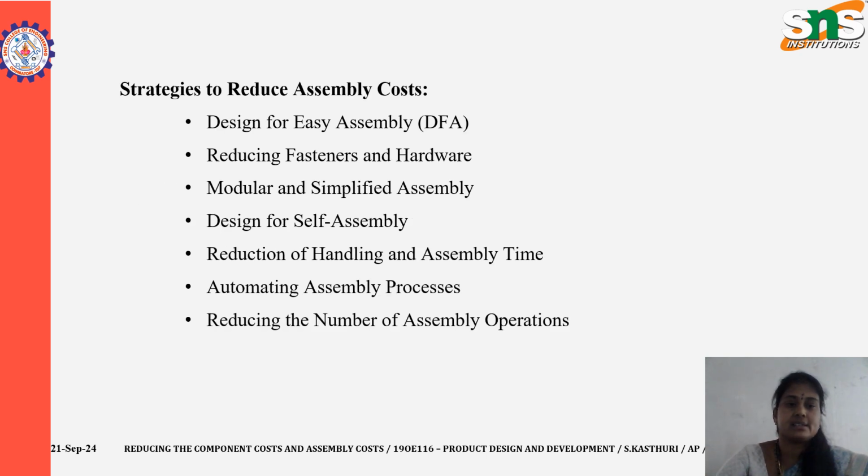The strategies to reduce the assembly cost are, first, design for easy assembly, DFA. It simplifies the assembly process by designing parts that are easy to handle, position and assemble. Reducing the complexity of assembly cuts down on labor time, errors and overall assembly cost.